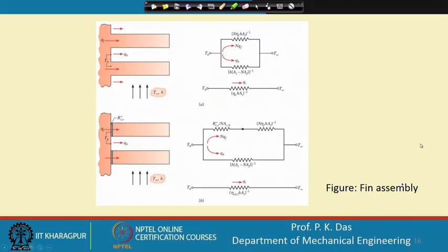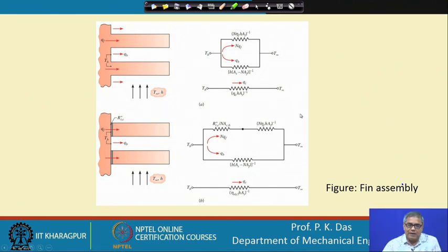Here I can tell you that by this time probably we are convinced that though in heat transfer books, and I have also done the same way, we have analyzed a single fin, we never use a single fin. In a heat exchanger we use a large number of fins, we use a fin surface. If you recall, that is why we calculated the surface efficiency where there are a number of fins. We did this one or two lectures before.